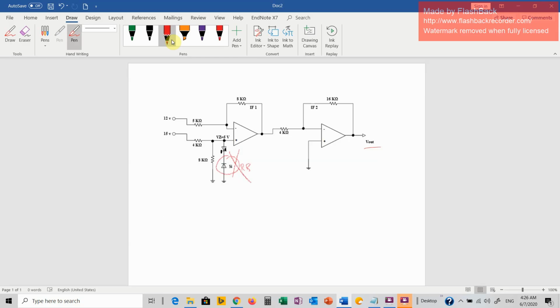That means you don't have to be worried about this branch because you have a silicon diode in reverse bias mode, and whatever the voltage is provided here, as long as it is DC, you don't need to worry about it. So the whole branch here is not working in this case, and you can just ignore it and proceed without worrying about this Zener diode anymore.